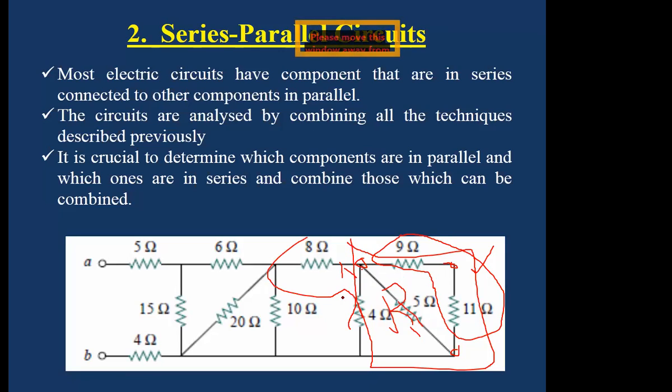Simplify any part which you see is in parallel or is in series. So from here, you can realize that the 10 ohm and the 20 ohm share two common points. So these two are now in parallel. You can combine them using the laws that you use. So these are some of the circuits that you will meet in practice, where you have to be able to simplify the circuit using series parallel network solutions.